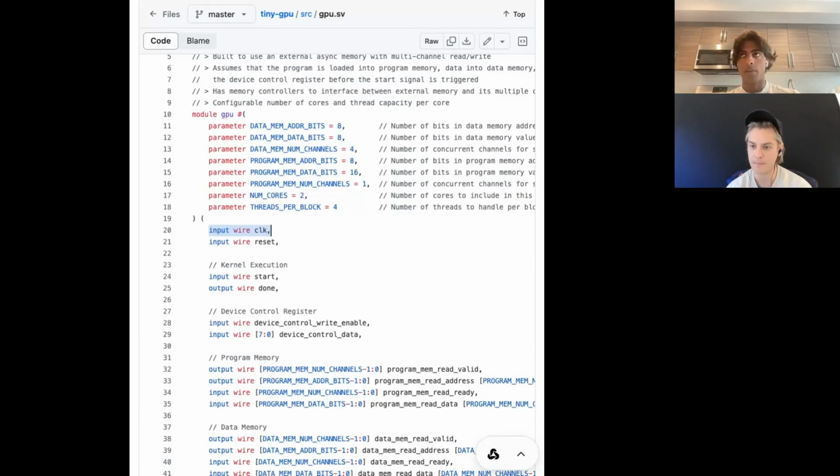Yeah, I would say that's more on the fabrication layer. There are tons of local defects, which is actually one of the biggest problems in the fabrication industry. That's why contamination control is such a big thing, because as you start scaling down the size of individual transistors, smaller and smaller defects that didn't matter before can actually break everything because they can get in the way of gates. There are tons of different places in the chip where a contaminant can just ruin the whole thing. And that's why the technology on actual fabrication has been advancing to smaller scales, and the contamination control technology has had to get better and better. But that being said, that's more a concern of the actual fabrication process.